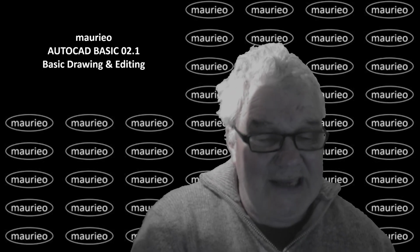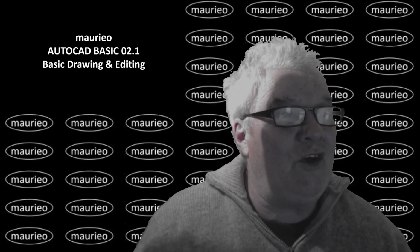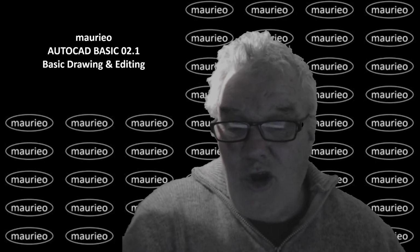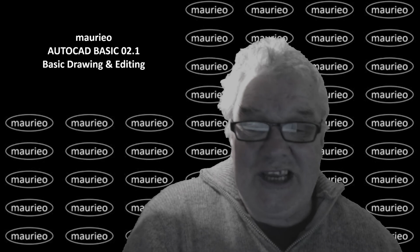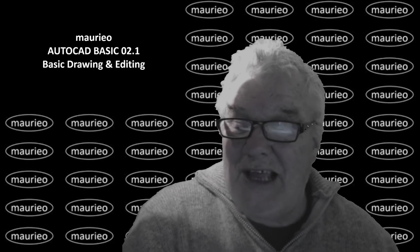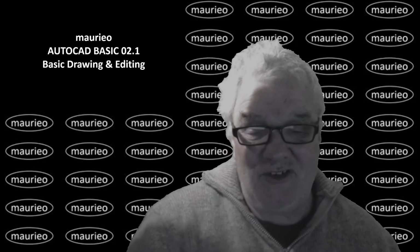Just go back, undo, and remember that. There's nothing to undo at the moment, but Control Z is a good friend, and the escape button, always escape, usually brings you back to square one, so that your crosshair is out of commands and all ready to go.